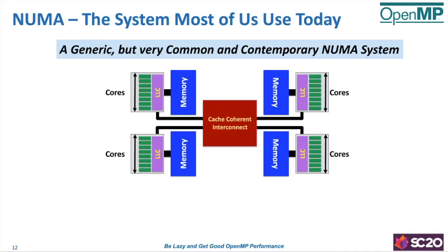But the most striking thing in this picture is that memory is physically distributed. Each node has 1/4, 25% of the memory. So a node owns a portion of the memory. The magic happens in that cache coherent interconnect. That knows what's happening in the system, and if you need your variable A, it'll figure out where it is, and it'll get it to you. That's really beautiful from a programming point of view. You don't know that the architecture is highly distributed under the hood. To you, it appears as a whole bunch of cores and one big memory. Underneath, it's different.